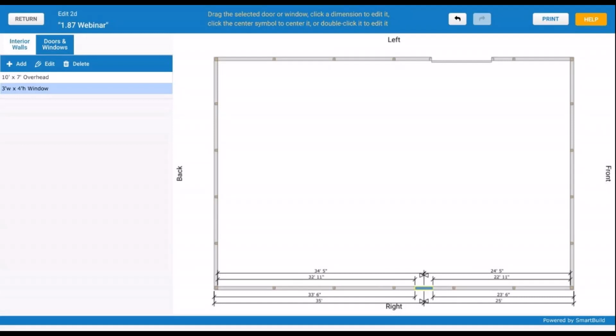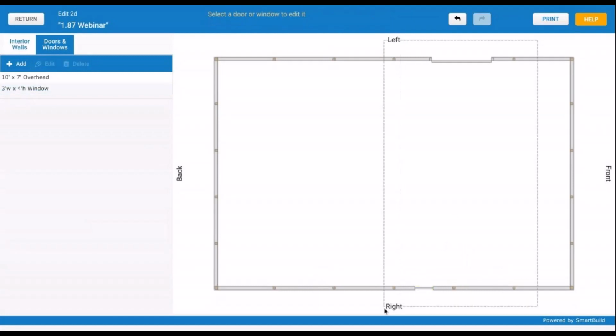So you can input these doors and windows. You can drag, select, and actually do multiple of these and hit delete. And this has been in there. Probably most of you have seen this, but just in case you haven't, you can come in here and add doors and windows here. It's quick to do this. That's not loading the model, and you have a little bit more flexibility and control over these dimensions. You can still add these and change these in the 3D model, but this is a nice quick way to do it.